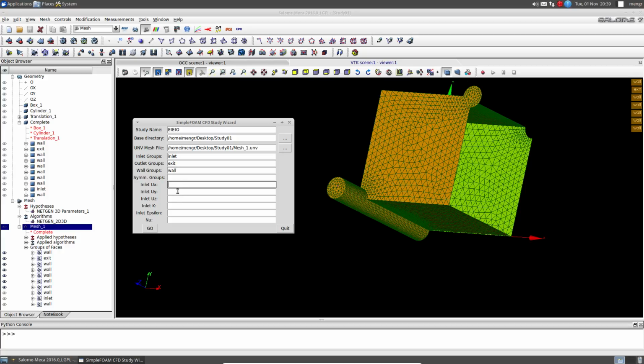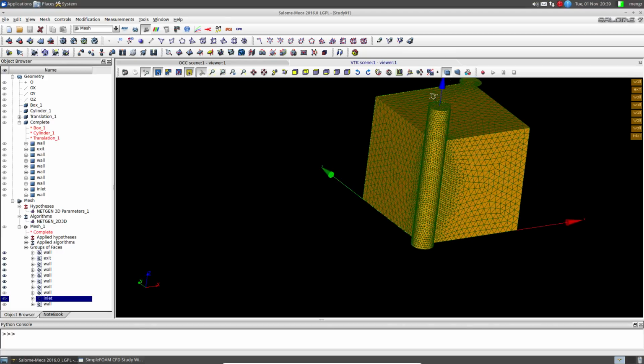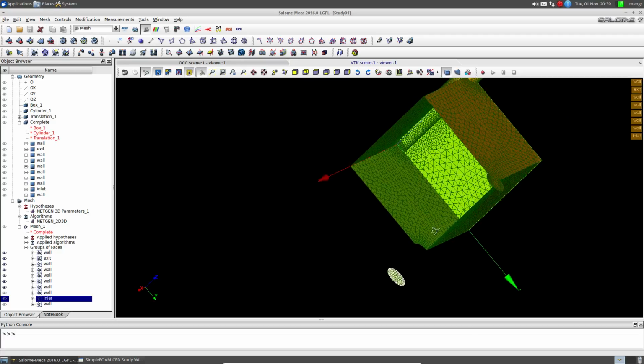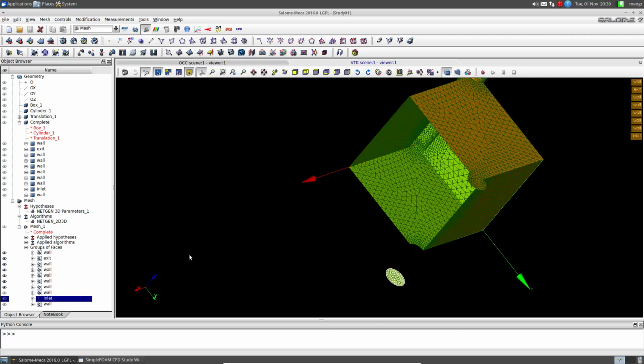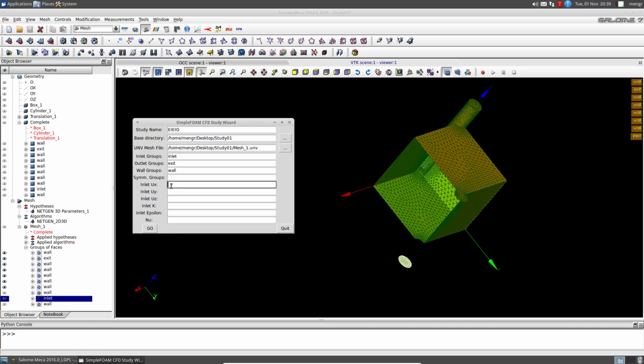Now the inlet velocity, if I come down here, I'm in the inlet here, taking a look at the inlet, turn this thing all the way around, try to orient it. So here in fact is the inlet. Let me turn it off and back on. So the key is you want it to be coming in, flying into here. This is the positive Z, so it should have positive Z velocity coming straight into here. So it should have 0, tab, 1, 0.0375, and then 0.0.